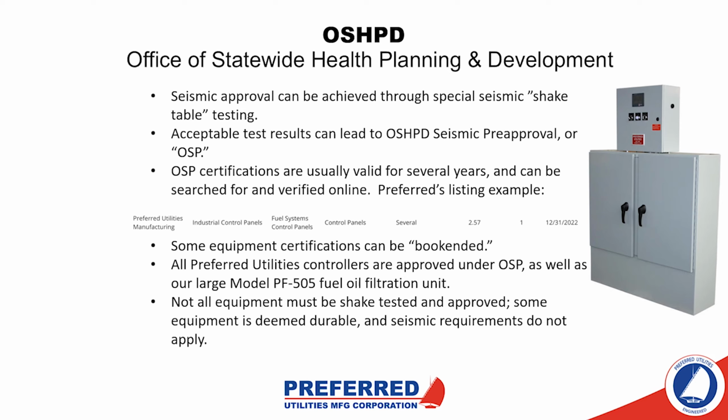Also, not all equipment must be shake tested and approved. Some equipment is deemed durable and seismic requirements do not apply. An OSHPD inspector will be able to advise as far as which equipment needs to be approved and does not, but generally we have a pretty good idea of it. Also, there are zones as well.